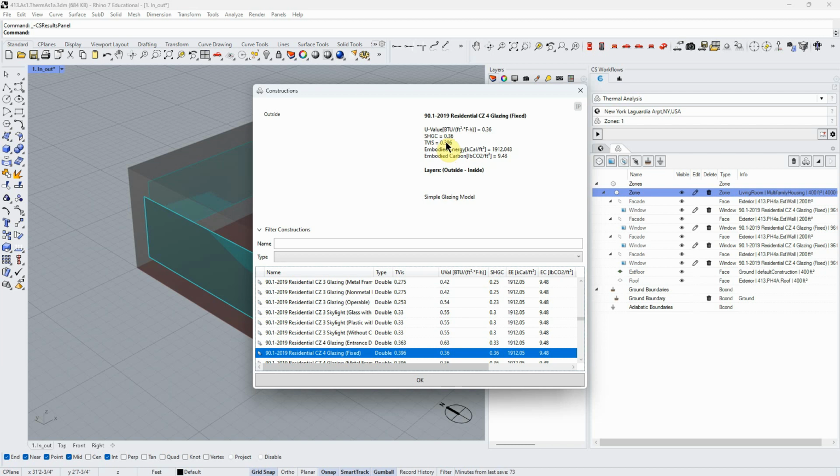We'll talk a lot about visual transmittance and daylighting in our daylighting analysis. Right now, in my experience, if you get this too low, you're not really talking about vision glass. It's very dark and it can be colored. Maybe that's what you want in your design, but just realize that that's another thing. If we're trying to have vision glass, you have to be conscious of this variable.